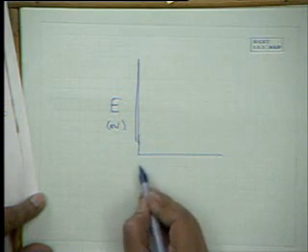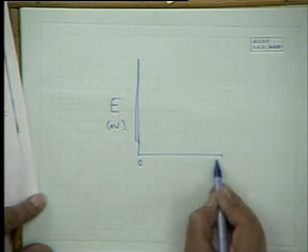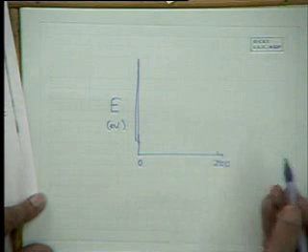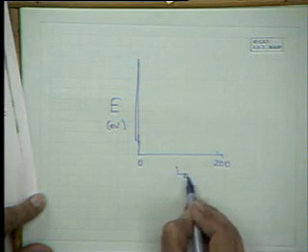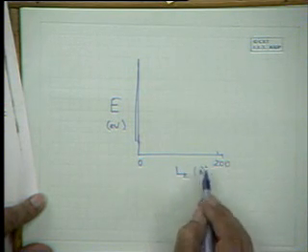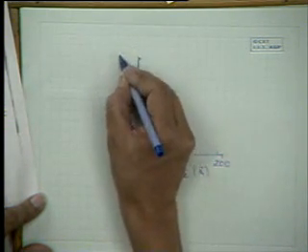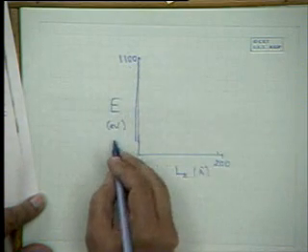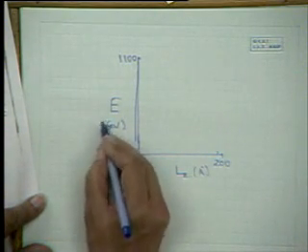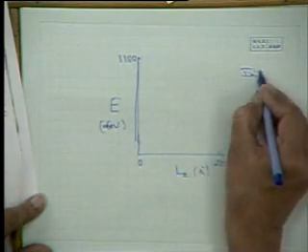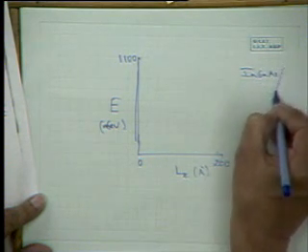we can make wells of different widths, going from 50 or even 20 or 30 to 200 angstroms, LZ. This is interesting: as you confine it, you can go up to 1100 meV. This is the well-known InGaAs-InP lattice matched system.